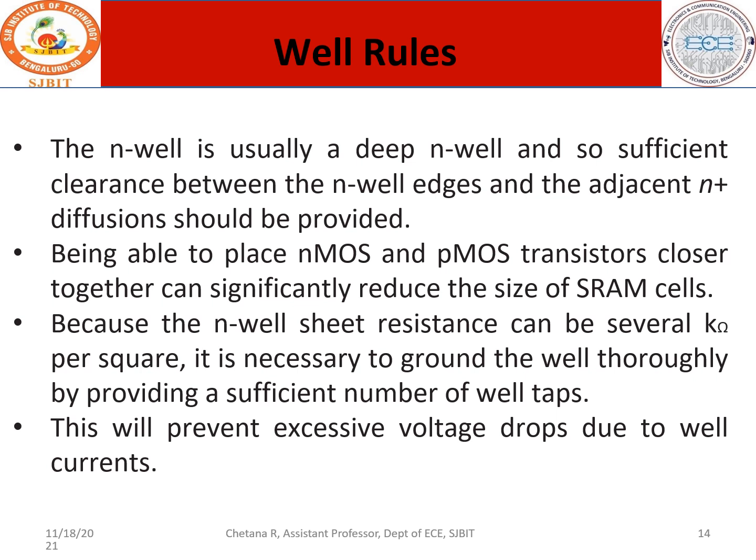Therefore it is necessary to ground the well. How do we ground the well? The only reason we are grounding the well is because it is high resistance. That is the reason most of the time the well structure is connected to VDD. This will prevent excessive voltage drops due to the well currents. Since resistance is high and current flow is less, that shouldn't create any drops. Therefore, it has to be well connected.